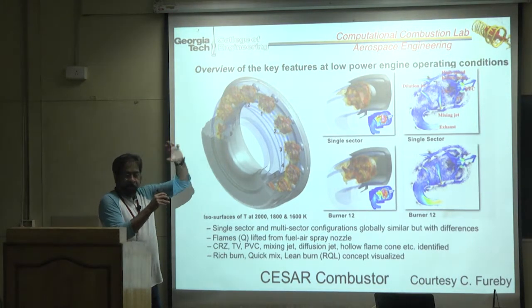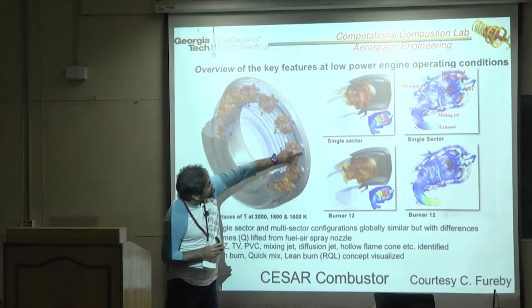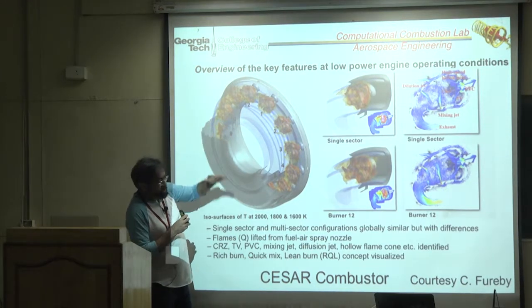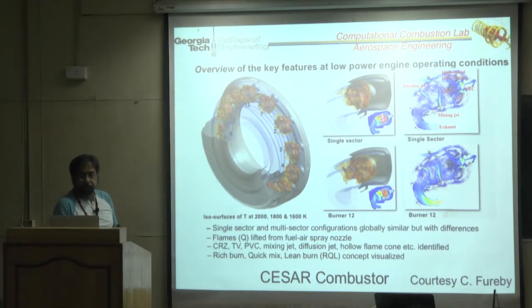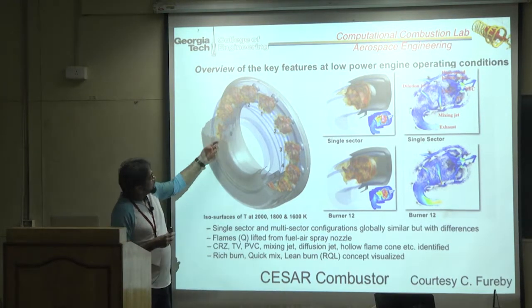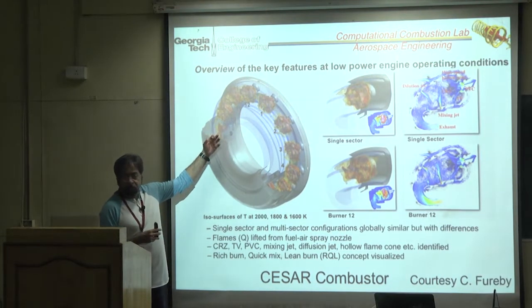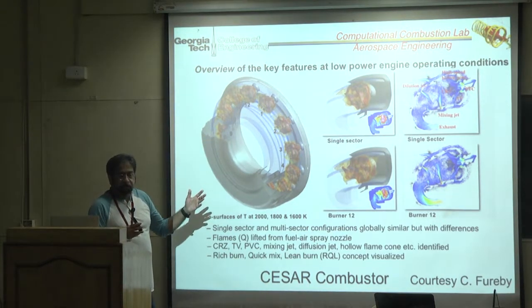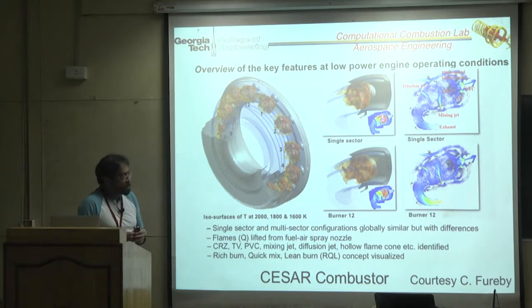annular burners. Like these are annular burners. That means this burner can talk to this burner because of the annular arrangement. But there were old designs where they were all separate to isolate them. So nowadays they actually do experiments where if it starts to go unstable, you tune one of the burners to operate at a different flow rate, and that kills the instability. But it's again not very well understood.